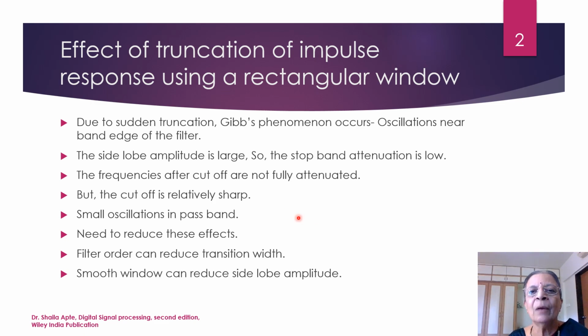We will just recapitulate whatever we have discussed in FIR filter design, that is the design of the brick wall filter. We discussed the brick wall filter and we said that let us replicate this brick wall filter on either side of pi and minus pi. So we'll have the replicated response around 3 pi, minus 3 pi and so on. And then we said that let us take the inverse transform, that will be the discrete time impulse response of the filter,